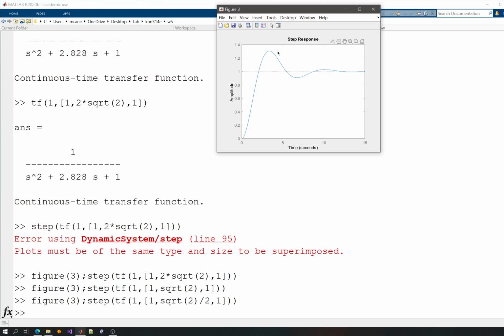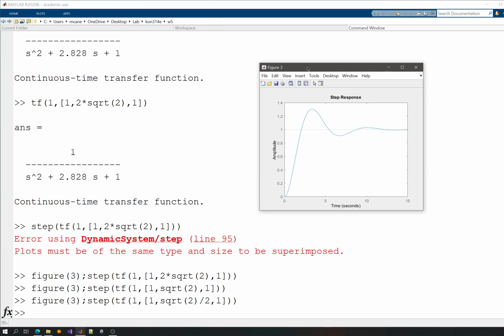If you use the Ziegler-Nichols method, you will most probably end up with a step response that looks like this. It has certain overshoot and a certain settling time, which is most of the time not ideal and not suiting your needs, but it is a solution that is provided without effort, and it is supposed to be a starting point for controller tuning.